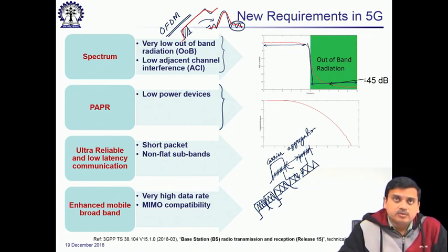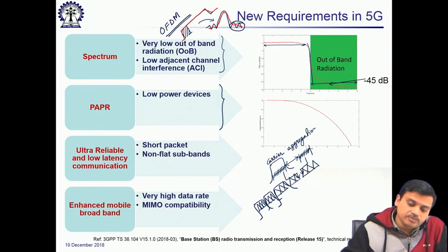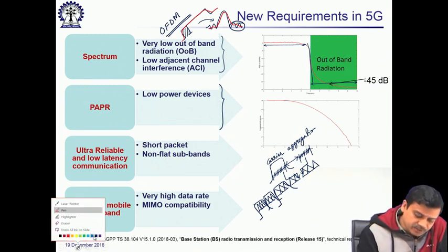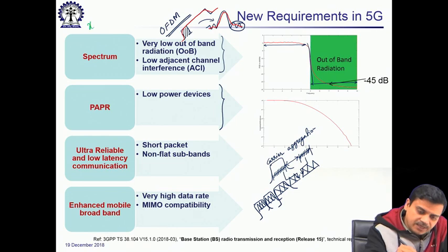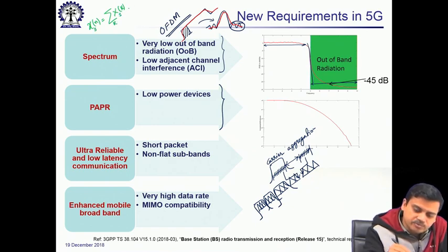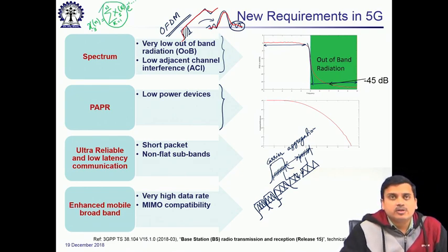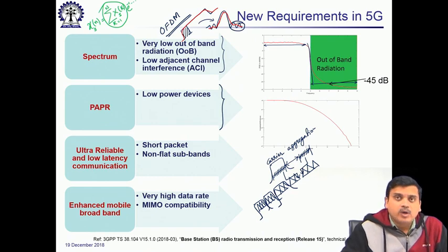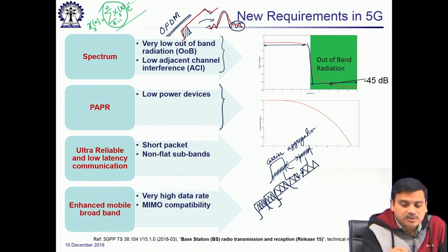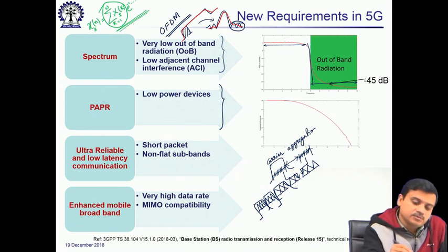The other aspect which one can think of is the PAPR, because we have discussed heavily when we were discussing OFDM that the signal x[n] is composed of a sum over X of k, where k is the subcarrier index, s is the OFDM symbol index, e to the power of something something. So, as many numbers that we add up, the peak to average power ratio grows, right. So, peak to average power ratio grows, all the disadvantages that we have mentioned come in. So, one desires a multi-carrier method. The moment you have multi-carrier, you cannot live without peak to average power ratio by default.